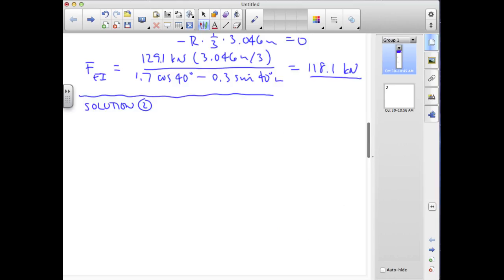So we'll go ahead now and draw our free body diagram again, now including the concrete between form DEG and the vertical cut. We already know this force P. We calculated that before. That was 127.1 kilonewtons, and it's 1 meter from the bottom.